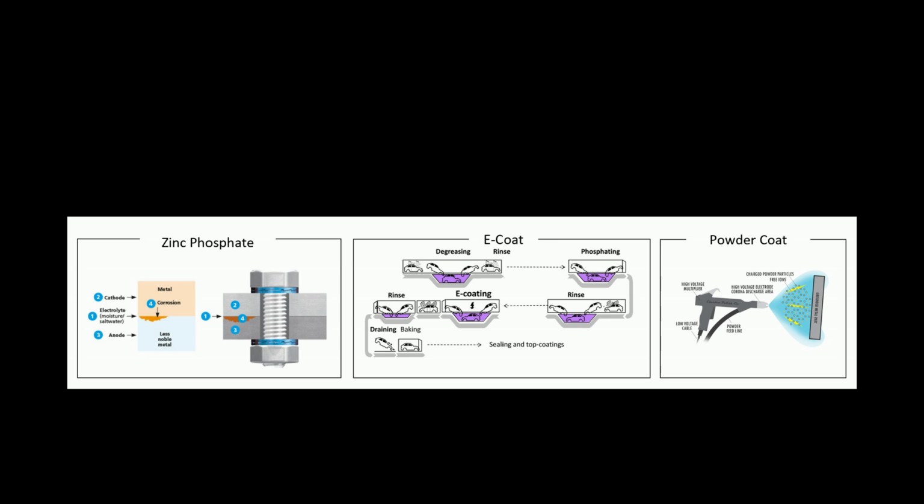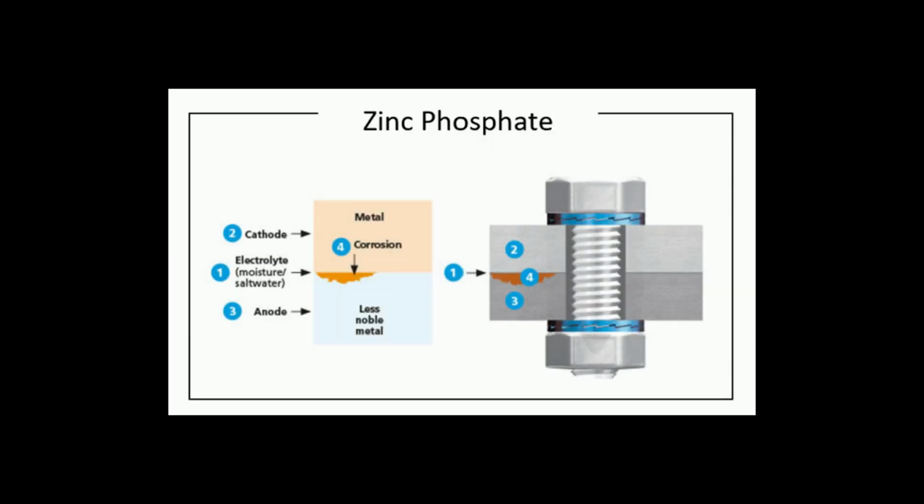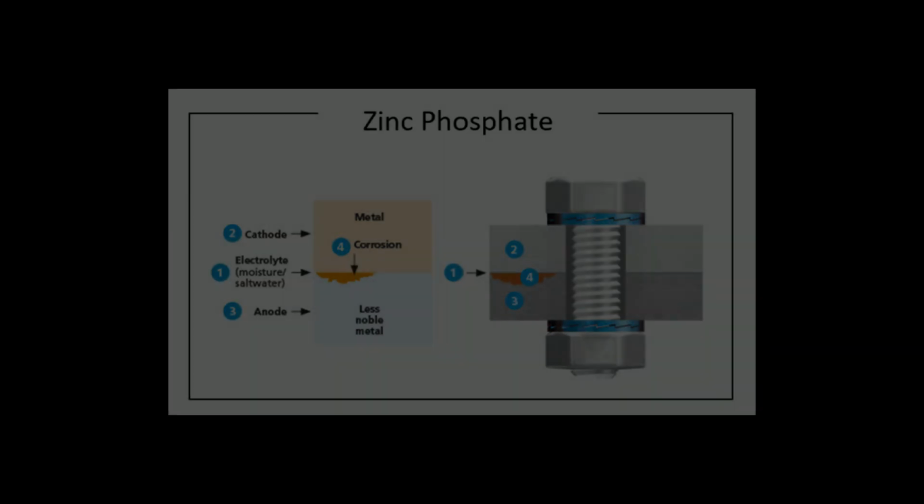Zinc phosphate is a chemically produced coating resistant to flaking as it modifies the rail's molecular structure. Typically sprayed onto rails, it slows paint debonding and is resistant to galvanic corrosion. Selecting appropriate treatments is essential for long-lasting frame rails. This non-conductive coating is an important option for enhancing rail durability and should be considered when selecting frame treatments.